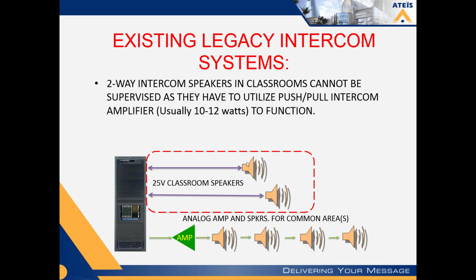To be able to do that, whenever these speakers are accessed, usually either if you have the older switch bank where you've got a big old toggle switch there in the rack or on a desktop console, when you flip that switch up to the intercom mode for whatever room or classroom you're calling, you're actually connecting that speaker to what we call an intercom or a push-pull amplifier. Another term you'll hear a lot is talkback amplifier. This is a smaller amplifier within the intercom system. They all use some semblance of the same thing.